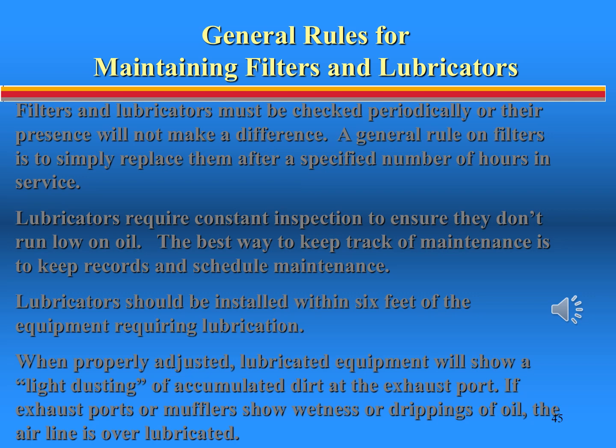Changing filters is a part of routine maintenance, and records should be kept to determine the best time to change them. When downstream pressure drops across filters are so large that machinery is affected, the time to change them has already passed. Pressure differential gauges are a good idea to monitor filter performance. Manufacturers specify filter performance to determine when pressure drops are excessive and require replacement of the element. Using specifications, we can determine the service life and set up an hour of operation schedule to change filters.